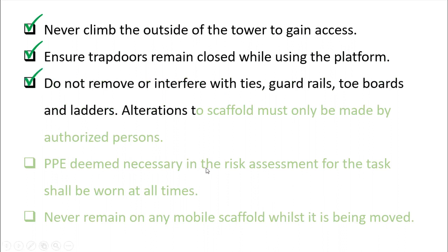Do not remove or interfere with ties, guardrails, toolboards, and ladder. Alteration to scaffold must only be made by authorized persons. Okay, so you are not allowed to alter your scaffold while you are using it. Coordinate always with the authorized person. So if you are the engineers, you need to make requests for a full-time scaffold authorized person.